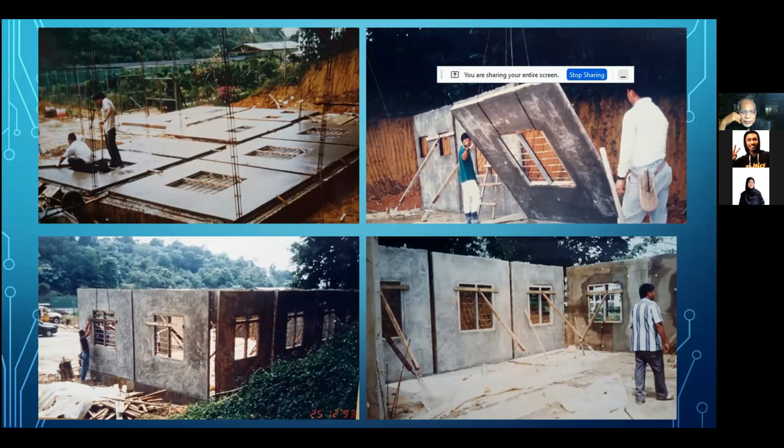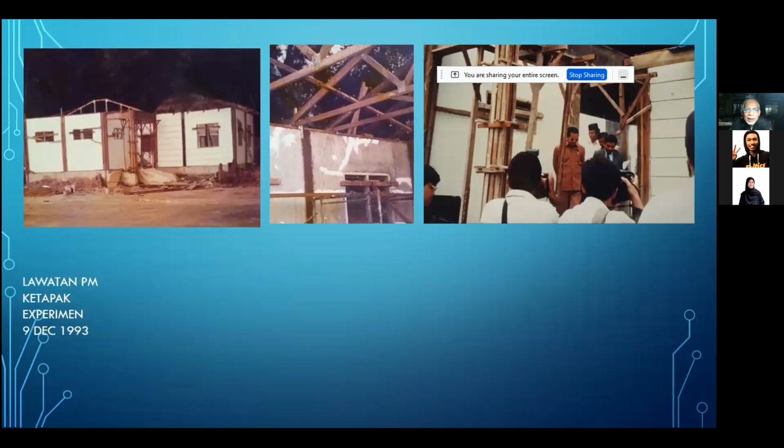Okay, so the reinforcement there is basically to take up the column. So we just put our minimum size of formwork there, and then we pour the concrete. Okay, we pour the concrete. This is when we're doing it. So we pour the concrete there. So now the columns will be up and the walls will be up.